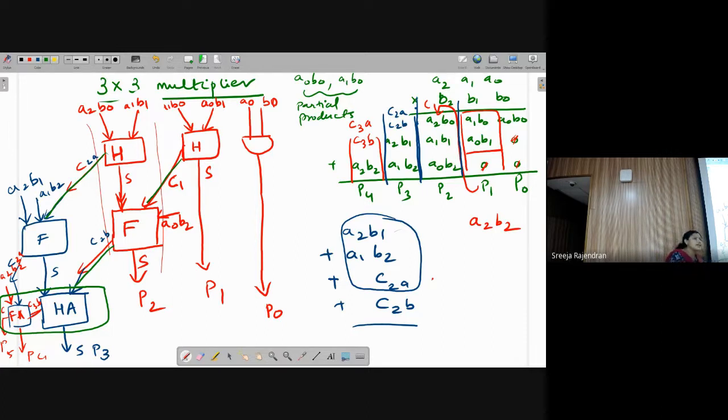So this happens like a serial adder, from one to the other. Unless this half adder output is available, I cannot do this full adder operation. Now, let me take row by row. This is row 1. In row 1, can I do all these operations in parallel or not? Yes, I can do them separately because none of them depends on a previous stage. There is no carry incoming, there are no connecting lines between them. No input is coming from this half adder to this.